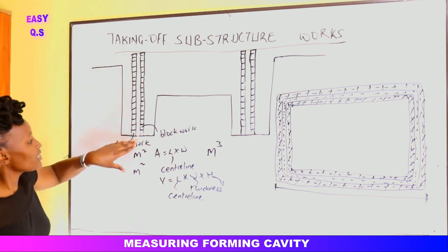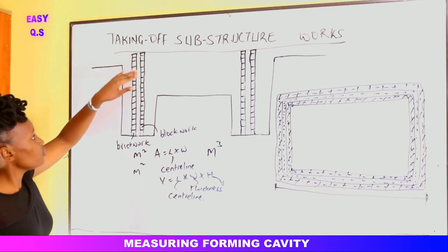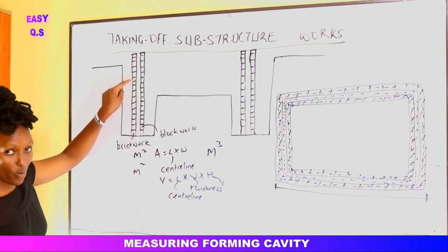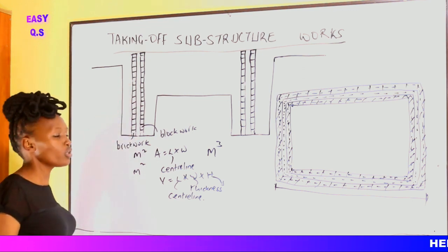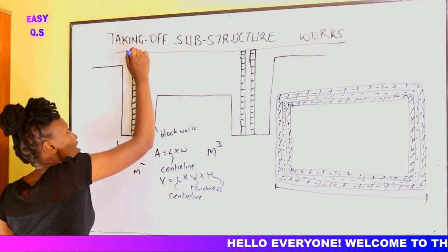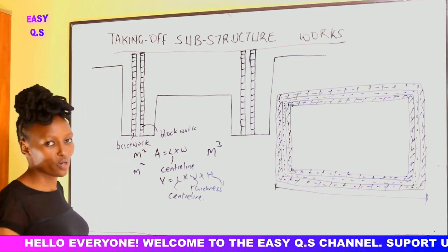The wall starts from the foundation, they go up to the top. So we do not have the concrete coming to the wall. So what we do to prevent that water from the foundations going up the building, we place the DPC on top of the wall, then we continue building the superstructure walls.